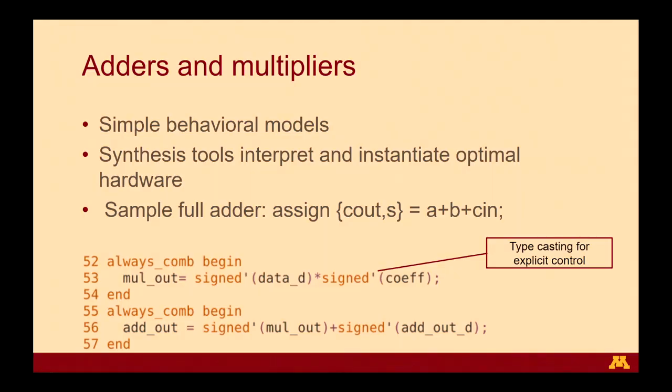So continuing with more examples of combinatorial logic. This is an adder and a multiplier, designed as pure combinatorial logic. Here we are using a behavioral model to design this. If you require, you could also do it by data flow, using well-known multipliers like a Booth multiplier. But in this particular case, the tools are smart enough to understand that when you have these sorts of operations, they will internally design a multiplier based on the requirement.